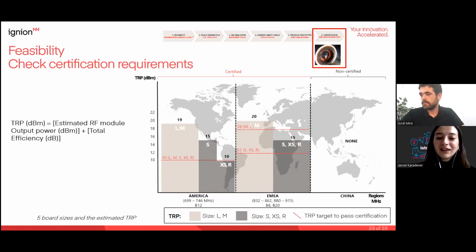Another question. Can I use a single Virtual Antenna for both cellular and GNSS? If yes, should I design a separate matching network for every frequency band, such as GNSS, GSM, narrowband IoT, and LTE-M? I think Thingy:91 is a good example for that question. Yes, I recommend you go to the application note section.